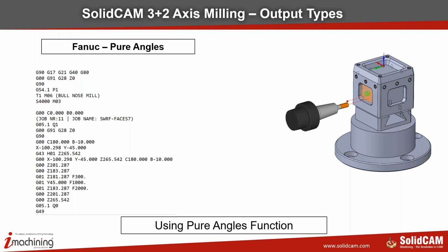So all those shifts and rotations have to be calculated by the CAM software, and then the calculated Gcode needs to be sent to the machine, and the machine will simply move to those coordinates, or the controller will move the machine to those coordinates. It will rotate and it will move to the new coordinates. The advantage here is that the operator and the user can actually see the program and visualize what is happening. Okay, but there's a big disadvantage to it.